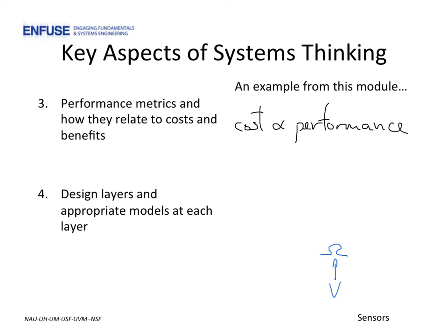That change in resistance is used to determine the strain in the gauge, which we argue is equivalent to the strain in the structure that the gauge is bonded to. It is that strain, accounting for Young's modulus, that gives us the applied force that we're interested in. A strain gauge is just one way to measure these forces. Other approaches, and perhaps less convenient, might include optical methods, but as long as they meet the upper layer objective, the approach is valid.